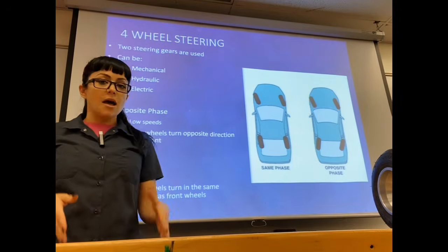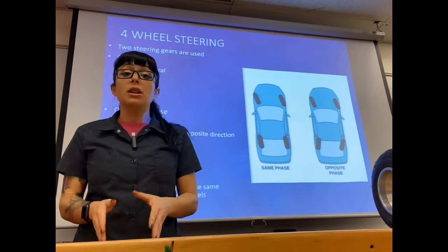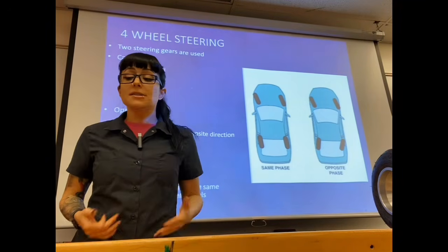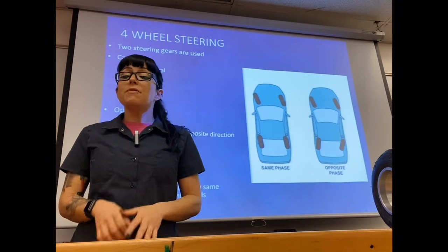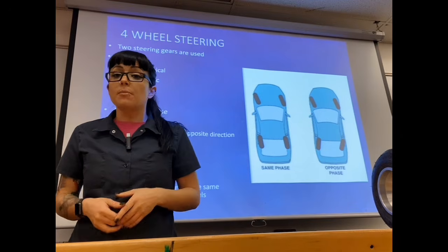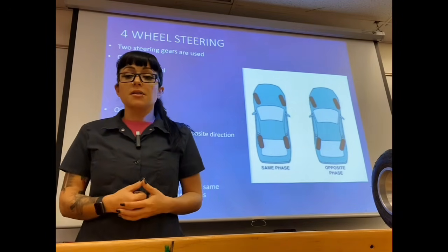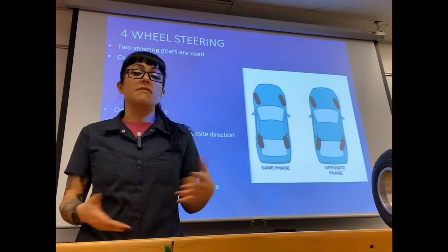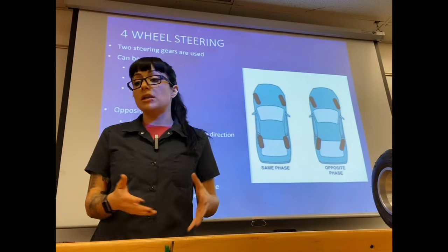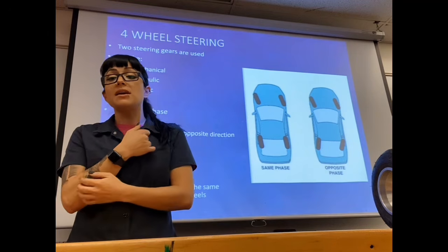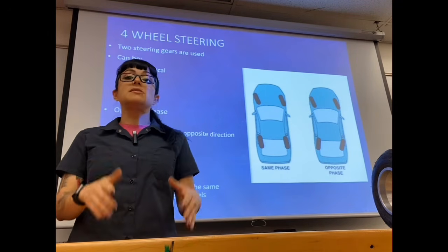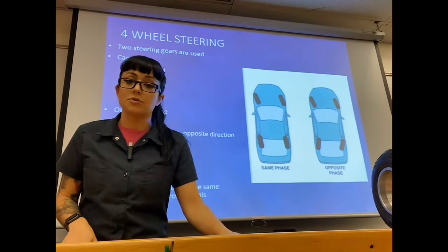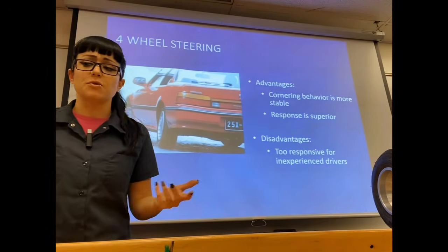So like I said, some manufacturer designs utilize both opposite phase and same phase, especially with an electric design. But some manufacturers may only utilize one. Like I believe Chevy utilized a design in their Silverados where they only had opposite phase at low speeds, and then obviously just wouldn't use it at high speeds. And some vehicle manufacturers made designs where they only used same phase at high speeds and it was disabled at low speeds. So it really depends from manufacturer to manufacturer.